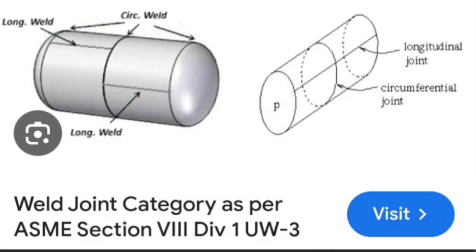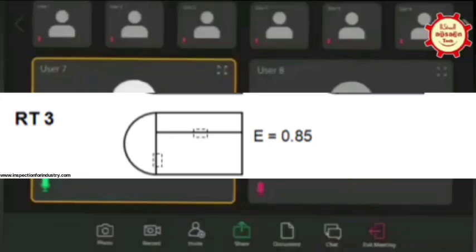Joint efficiency, all are given 0.85, okay. Or else, if we select the one spot, then the seam will be taken with joint efficiency 1. No, I think you should go with 0.85 only nowadays. For all long seam, short seam, everything we have to do.